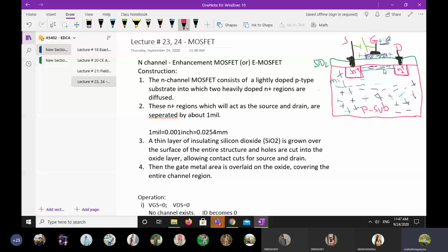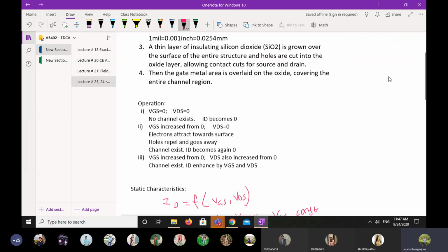Why will we not get the negative current? The electrons are moving from source to drain. Is it right? If we make VDS equal to 0, this drain voltage is not attracting the electrons, so the electrons are not coming out of the device. So there is no current, but maybe some internal repulsion will generate something. That is also positive, not negative.